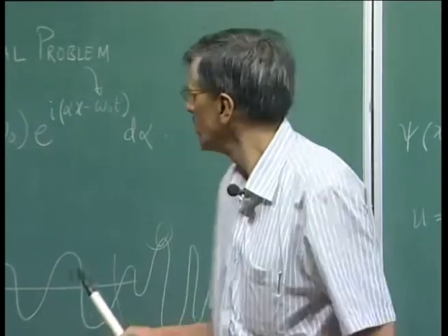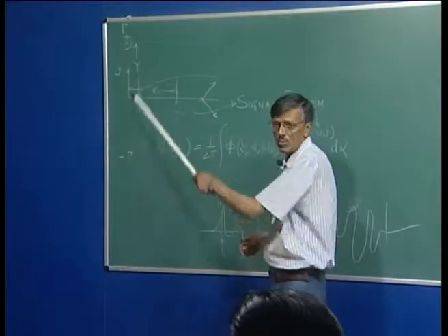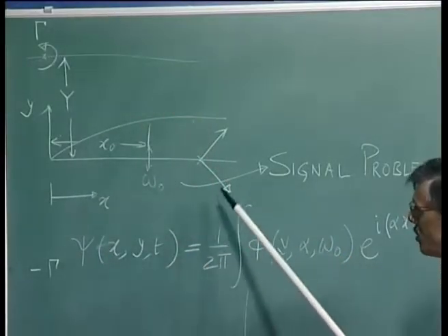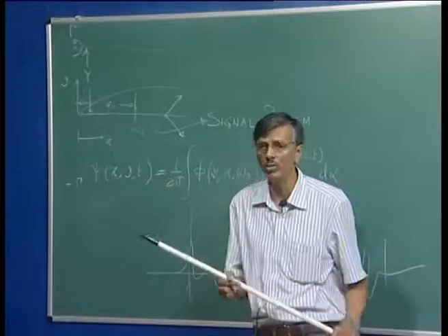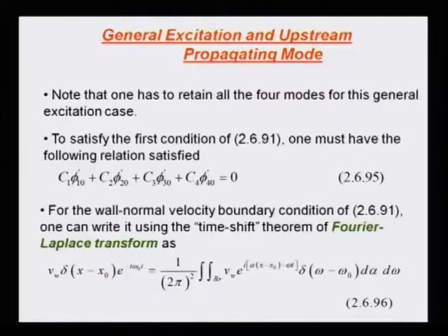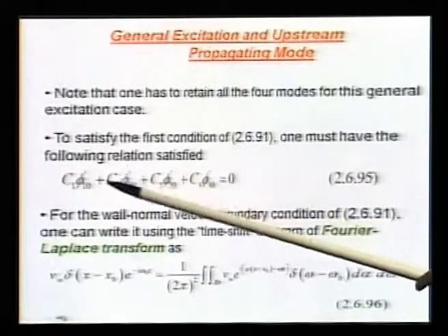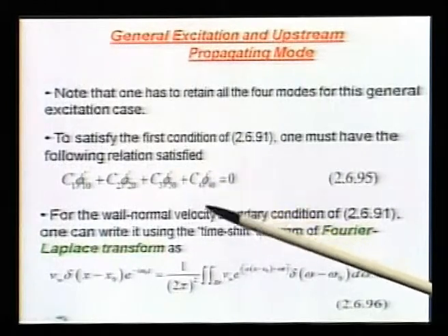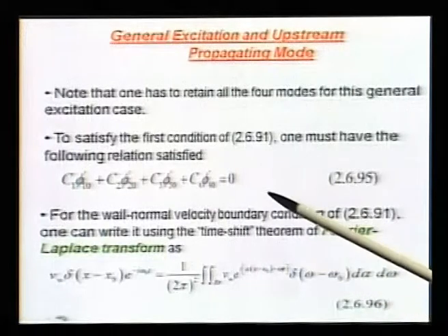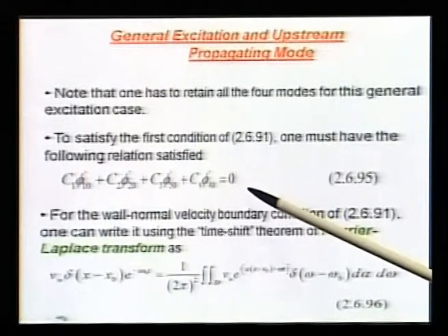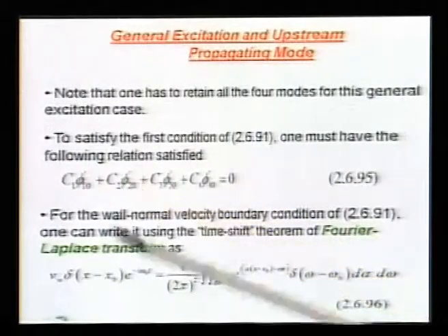See, like the inviscid solution corresponding to this gamma and its image gives rise to slip velocity, but still we are inside the boundary layer. We still should support a no slip condition. That is what we ensure by demanding that this C1, C2, C3, C4 should be such that the prime quantity, so that is del psi del y at the wall, should be equal to 0.